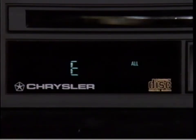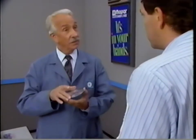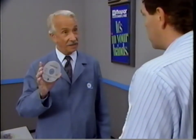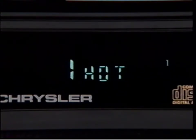Well, that could mean that the surface of the disc is dirty or clouded by moisture. The surface of the optical parts are clouded by moisture, or the disc was inserted with the label side down. In the case of the moisture problems, keep the unit on for at least 30 minutes or until the moisture evaporates. The CD player also will display hot when its temperature exceeds 140 degrees Fahrenheit.